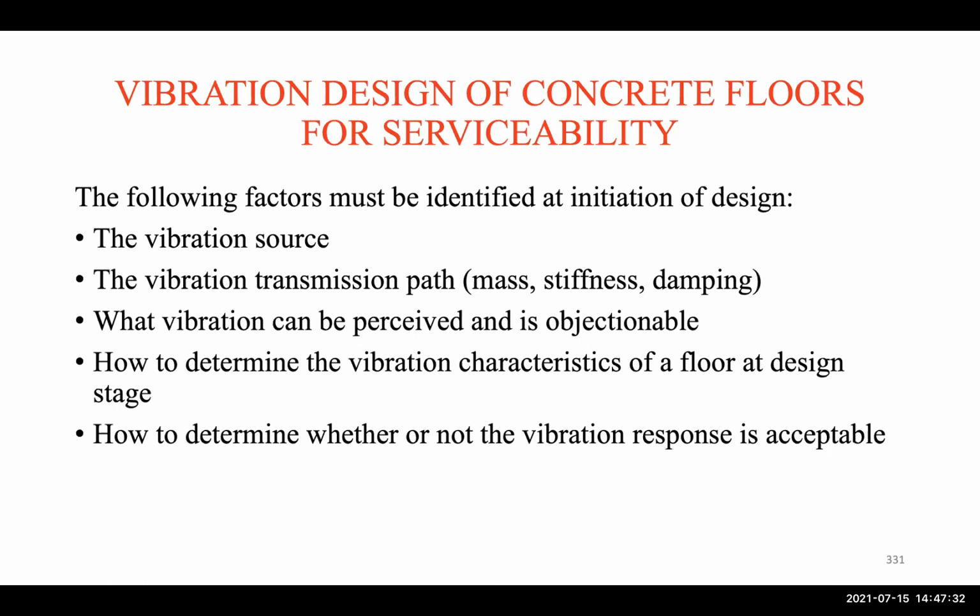Is it in the mass? Is it in the stiffness? Is it in the damping? Because this will lead to the solution. This will lead to the solution to increase the stiffness, or increase the mass, or increase the damping, or a combination. It could be a combination. Okay, and then how to determine the vibration characteristics of a floor at a design stage.